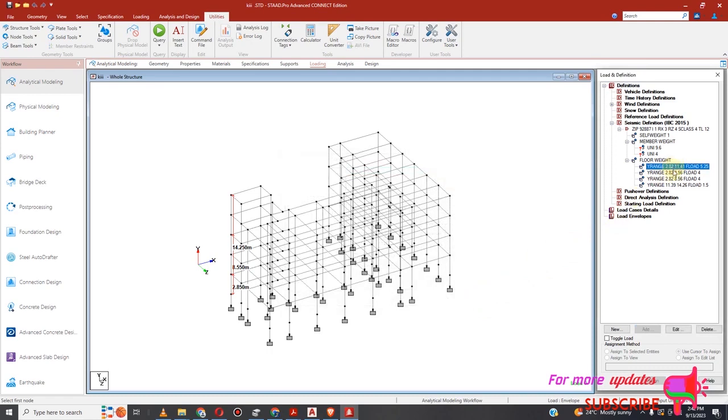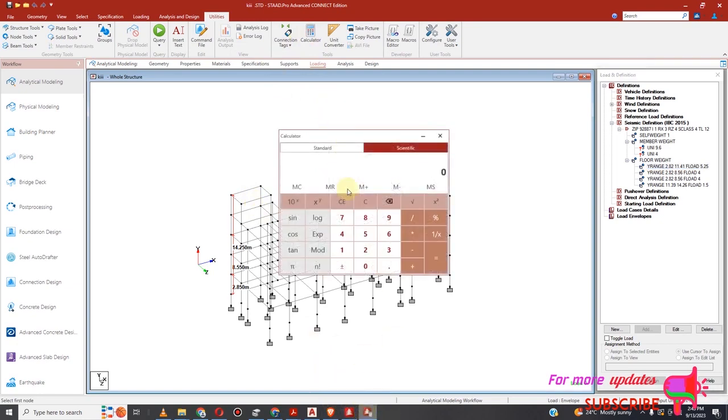Remember this one should go up also to the roof. No, this one is water tank, so we should calculate the weight of the water tank plus the unit weight of the slab. Let's assume a 3000 liters tank. That is 3000 kgs multiplied by 10 divided by 1000.